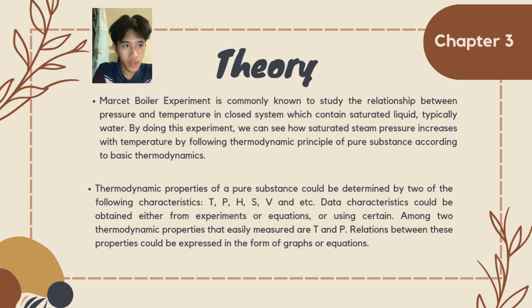The theory and working principle of this experiment. First one is the Marcet boiler experiment. It is commonly known to study the relationship between pressure and temperature in a closed system, which contains saturated liquid, and it's typically water. So by doing this experiment, we can see how the saturated steam pressure increases with temperature by following the thermodynamic principle of pure substance according to basic thermodynamics.